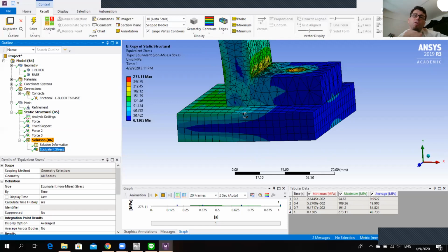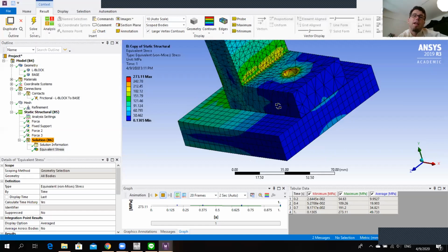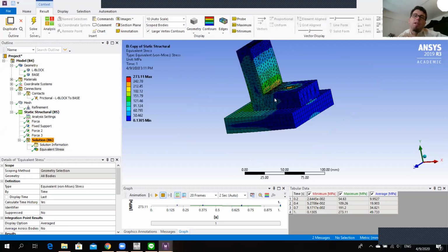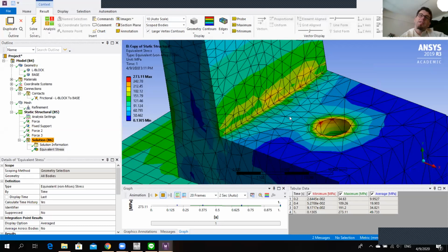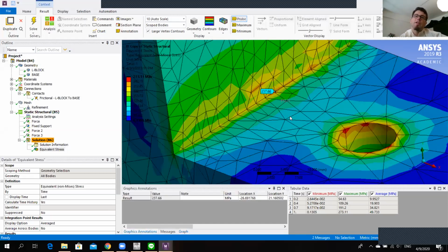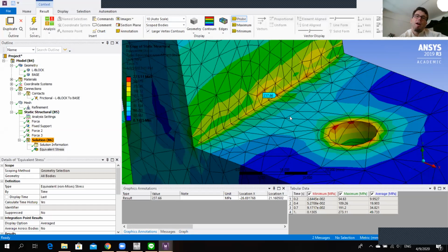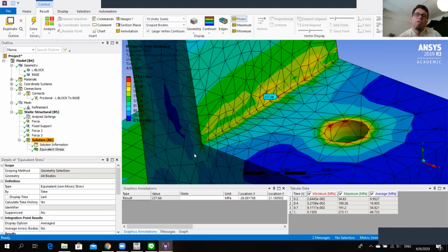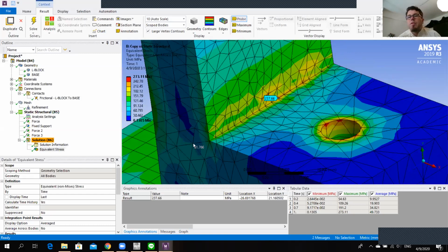So the stress level around the nodes on the edge is around 210, maybe 220 megapascal again, as we saw in the preview. Just judging by the color, you see some of the middle nodes are just getting orange, so to speak. And if you look at the scale, that means they're around 210, 215 megapascal, while the others are still yellow, so under that value. So again, as you just did, you just pick up the stress value at the node. You could look at all of these, and I guess maybe the average value would be pretty close to the other model that we had.